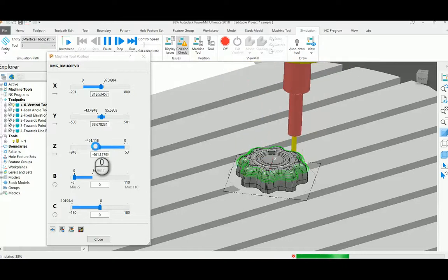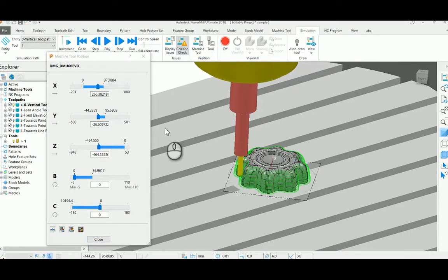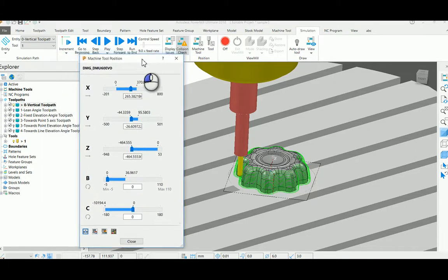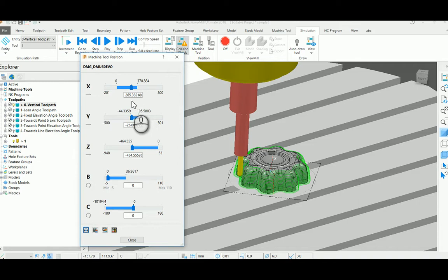Here our concern will be the tool length. As the die depth is more, we have to have a longer tool overhang to complete the die, which will create chatter marks. If we have the feasibility of a 5-axis machine in our shop floor, then we could use the 5-axis rotary motions to control the length of the tool. So we can have a shorter tool length, and we can complete the entire die.